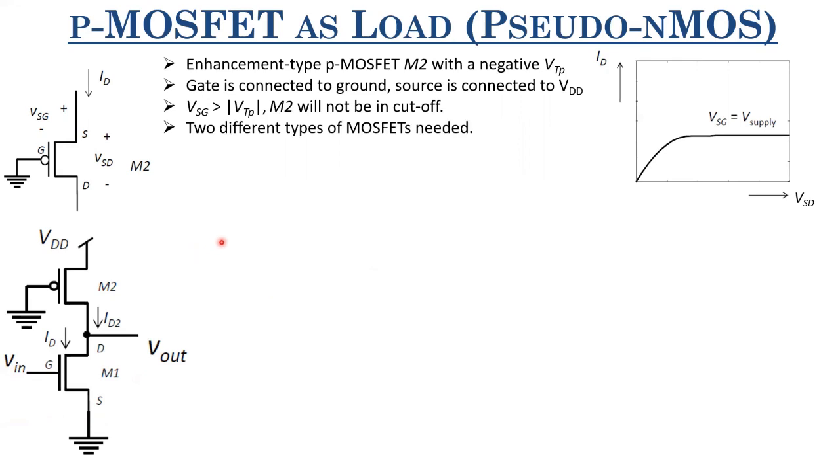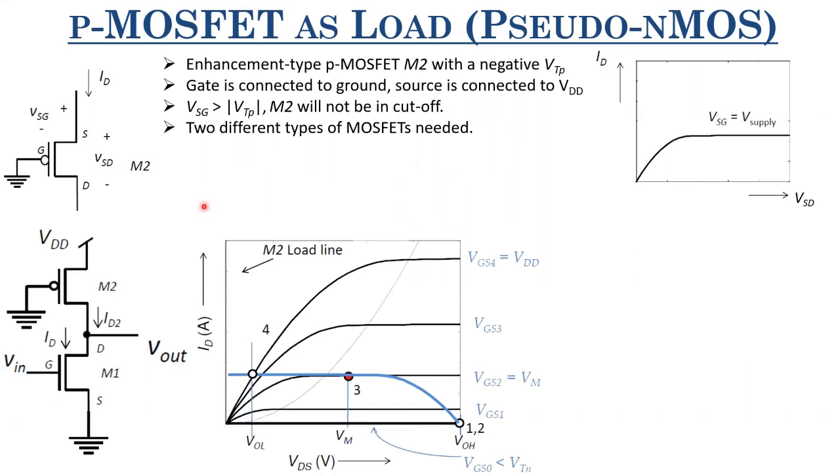As in the previous case, here also we have to make two different types of MOSFETs. As fabrication technology got better, we had the capability to make two different types of MOSFETs, and it led to a revolution, I would say. This eventually led to the invention of CMOS circuits, and circuit performance improved significantly. Even if realizing two different types of MOSFET meant two different masks and some process complexity, since the performance was so good, people went for it.